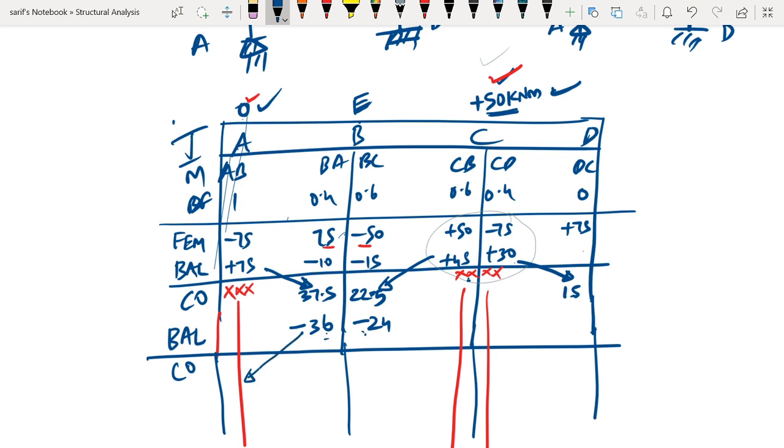The only two balancing moments are these two, and we can carry it over to here. However, carrying over is not permitted here because it has already satisfied its moment condition. Similarly, the other balancing moment is this. If we try to carry over to here, since it has already satisfied its moment condition, we do not have to carry over there also. So by the second balancing act itself, the beam has reached its final stage.